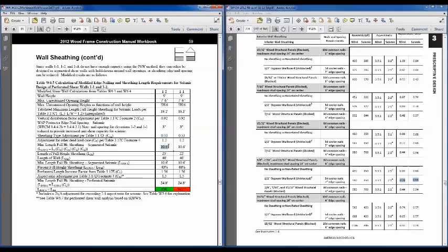And when we do that, our segmented length is now about 10 feet, and our perforated length, based on our perforated shear wall adjustment factor, is going to bump us back up to about 20, not quite 25 feet, and that works based on the length of full height shear wall that we've got in this wall. We've got 25 feet, so we come in just under on that bottom wall.